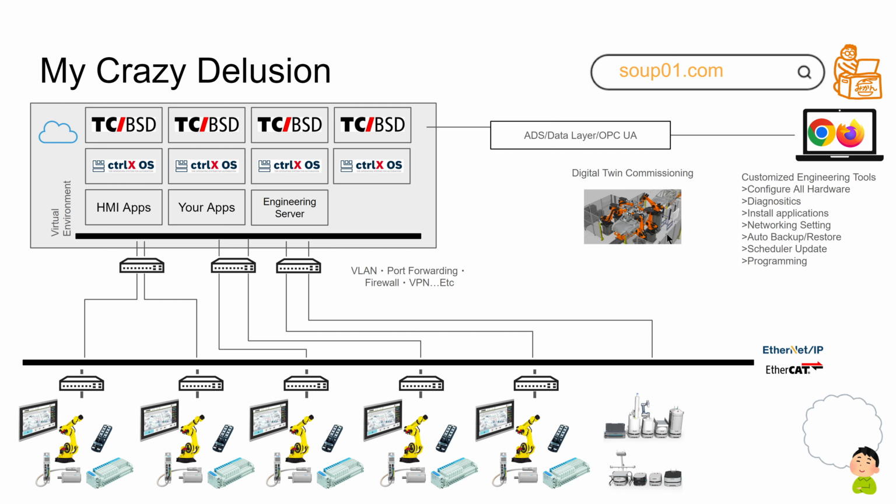And then there's a very big topic, digital twin commissioning. The same engineering stations connect to your local server. In your local server, depending on your next generation of line, you can build the images inside: what kind of apps and what kind of virtual PLC you should have. Then you can build it in a container or some virtual element and use a common interface for debugging. By using this, you can debug, do code generation and unit testing, all done here.